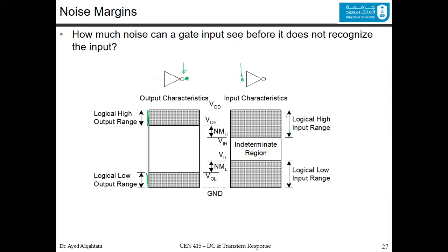Why are we giving more flexibility at this point and more restriction at this point? Because we have no idea what will happen when the current is moving through this wire. Maybe there will be noise, other effects, secondary effects like coupling and other things. So since you are just getting out from here, let's put more restriction to make sure that what comes out is really good in terms of logic 0 and logic 1.